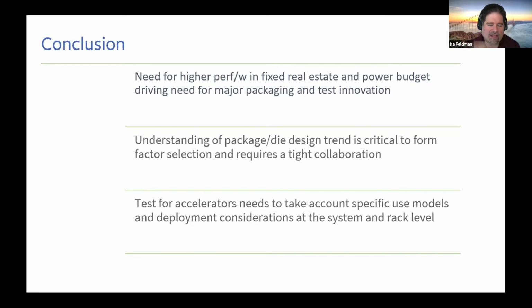So for the type of workload you're looking at, is there a general direction you think that needs to go? Yeah, I think clearly, if you look at some of the training platforms that we have disclosed at Open Compute, we do have larger accelerators like GPUs, which have co-packaged HBM memory. In this particular case, our need was more for capacity and not as much for bandwidth. We also wanted to be in a thermal envelope of around 15 to 20 watts, which is not very amenable to co-packaging things like HBM. So it was a combination of the workload need and the form factor to fit into our server infrastructure that led us in this direction.